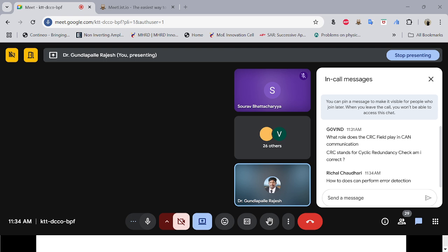Right. So the frame length varies due to bit stuffing. If the data field has 0 bytes and there is no bit stuffing, the frame will usually be 47 bits. If you are using 8 bytes, the maximum, there will be 111 bits.